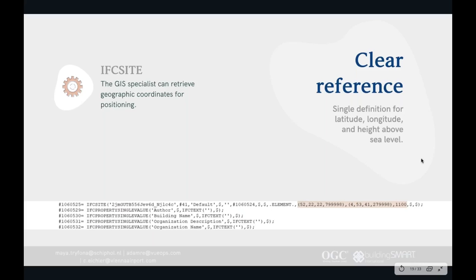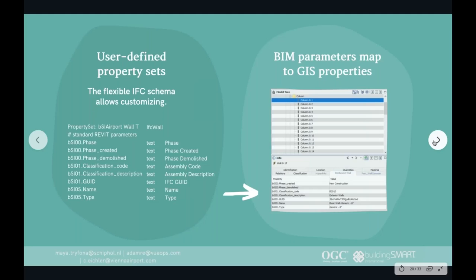And next, after covering the export settings, the units, and the georeferencing part, we are moving through our steps to the attributes. So for some airport-specific asset types, which are not covered in the IFC standard yet, like the automated border control systems, we are using the customization which is available from the IFC standard, like the IfcBuildingElementProxy entity, the custom property sets, custom properties, and the user-defined enumeration types.